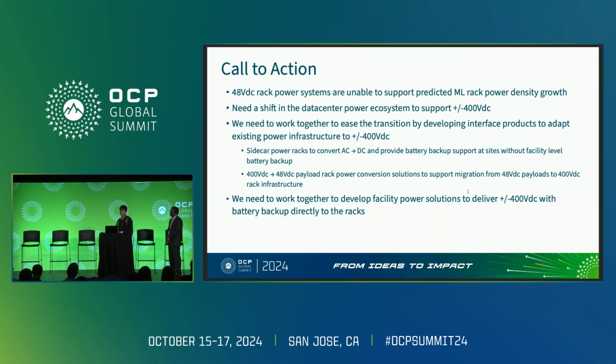After that is the system we know that we have been using for 10 years. So that's one approach. The other approach is that we can convert 400 volts to 12 volts and then do power distribution. At the end of the day, it's a trade-off that depends on the system. Maybe it's a matter of how much density you want to push for the module versus the power distribution on the board, and the overall efficiency and the ecosystem.